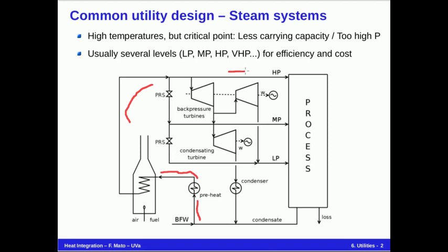This is directly used to heat the system, while other parts produce work over back pressure turbines, finishing in an intermediate medium pressure or a final low pressure steam that are used to heat the system at different levels, or through a condensing turbine without producing a steam but a liquid and get out most of the shaft work.